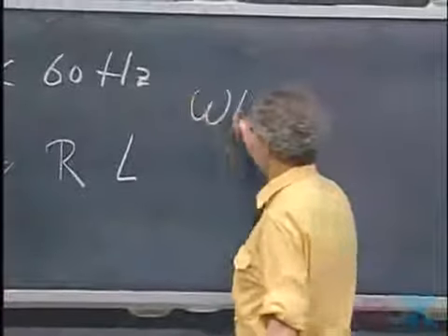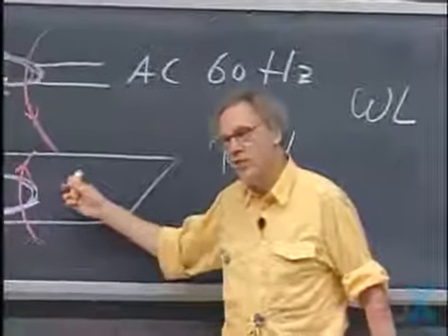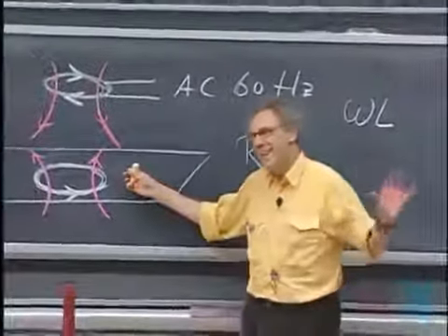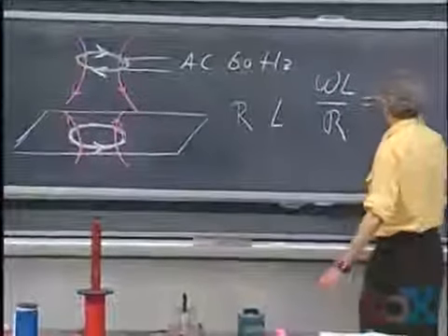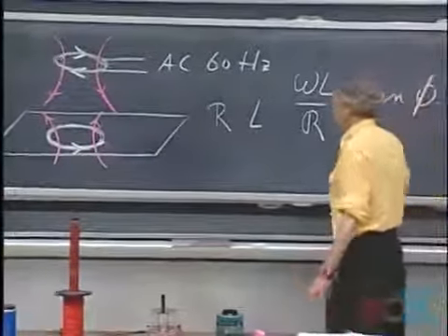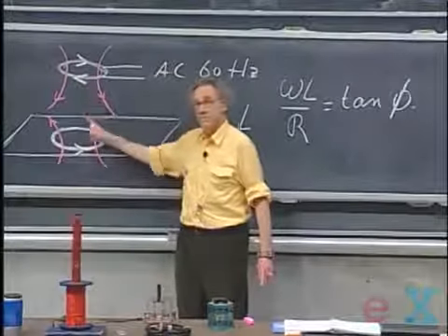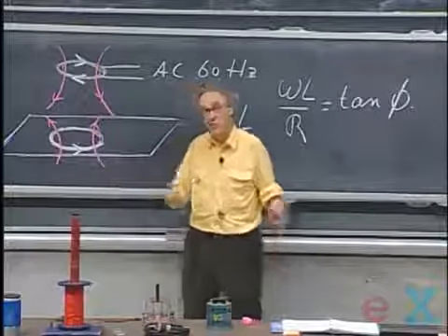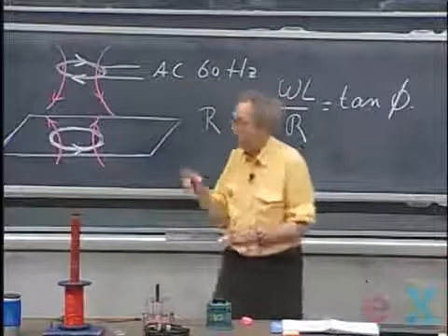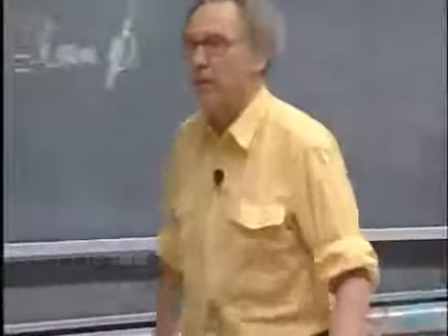And so in this conductor, the induced current is delayed by a phase angle, given by this equation, is delayed over the induced EMF. The EMF is immediately coupled to what this coil is doing, but the induced current is delayed. And I have something that will allow you to see that perhaps in even more detail.